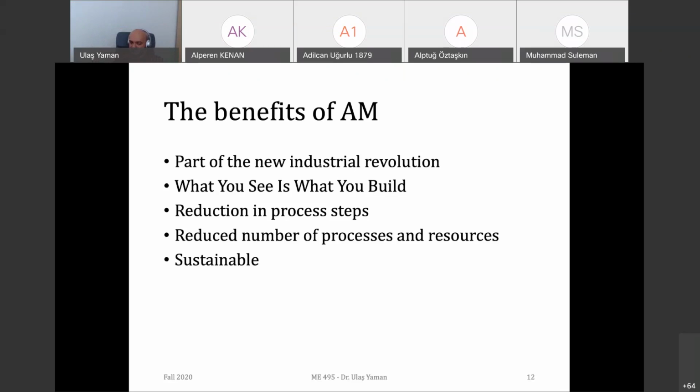But 3D printing is not as fast as, let's say, injection molding. Sure, yes. Injection molding, especially for such plastic parts, if you have a mass production case, it's better you use injection molding, but if it's, let's say, around 50 of this product or hundreds of them, and if you have a large printing area, you may build maybe tens of this part at the same time.